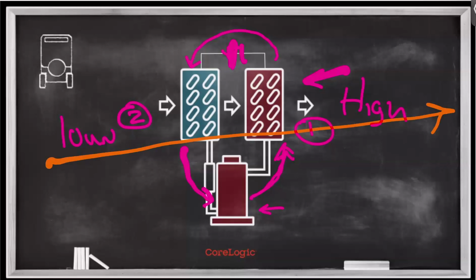Now take the air from your drying environment and run that air straight across both of these coils. You have air that is warm and humid, and you run that warm, humid air across the first coil. That first coil, its job is to remove energy because it's cold, right? So it's going to draw energy out of that air. And as it does so, it removes energy from the moisture in that air and causes it to condense. The same thing that happens when you take a cold soda can and put it on your counter on a hot, humid August day. That soda can is absorbing the energy out of the air and causing the moisture in the air to sweat onto the surface, right? And that's in essence what's happening on that first coil.